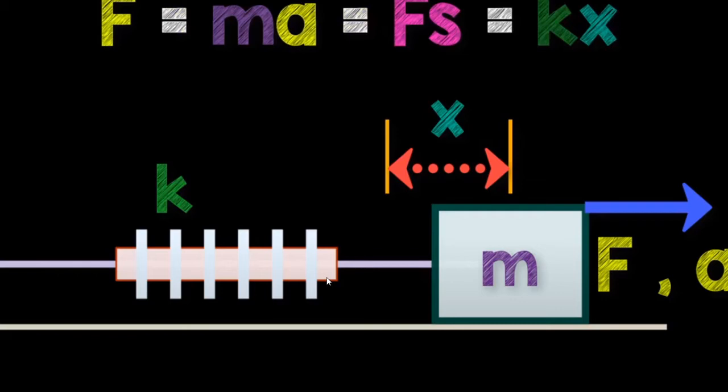You can also use capacitance sensing. For example, if you have a capacitor and the distance between the two plates changes, then the capacitance also changes. So based on the capacitance change, you can measure the distance change. This is another kind of sensing method for distance. And we also have another called inductance. I will not introduce too much, but why do we use this kind of thing? Because we cannot build a very big accelerometer. We want it wearable, so normally the dimension is very small. So we need to use this kind of sensing technology at the nanometer scale.